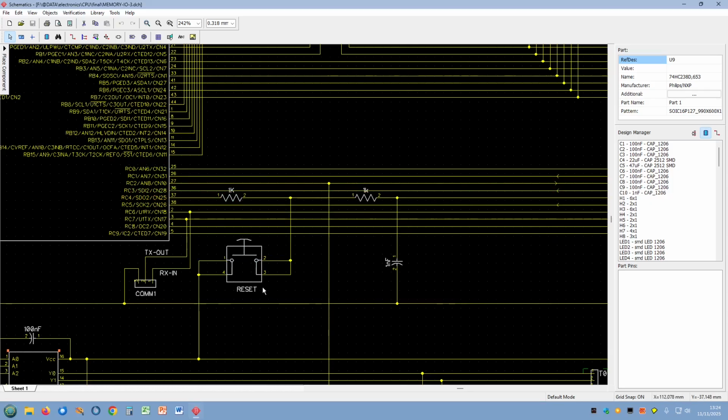Because when you do a reset, this is going to try and do a reset as well, and then you could have conflicting outputs on here, and it will damage the output of the microcontroller. So by putting a resistor there, I could have 0 here and 5 volts there, and that's 5 milliamps, which this can handle anyhow. So that stops you damaging the microcontroller.